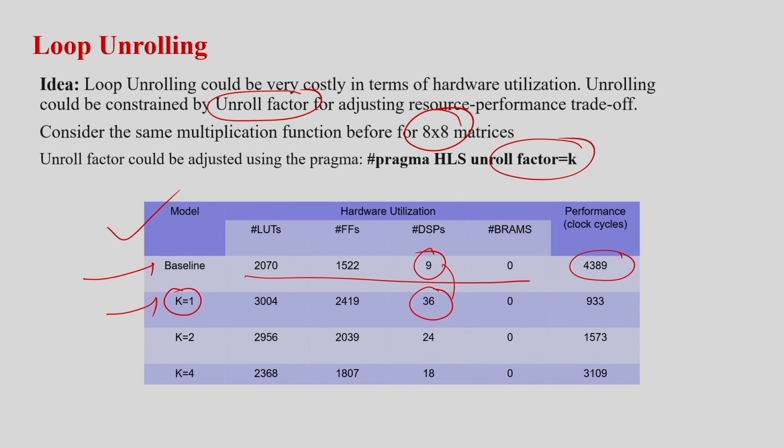If I unroll, there will be 8 multiplications within the inner loop, but that is not 8 times. Again, the reason is what I have explained. Now, if I apply an unroll factor, you can see here it is about 2.5 times, and the reduction in clock cycles is almost 4.5x, right.